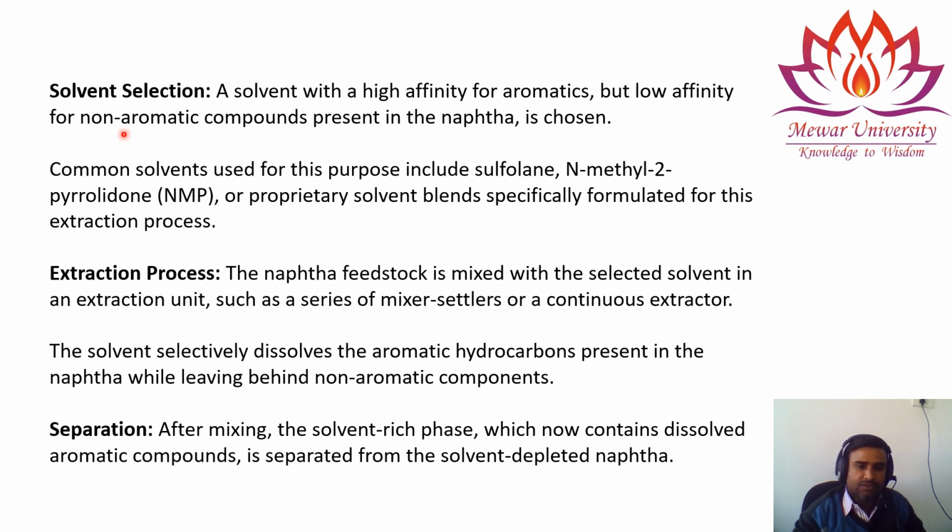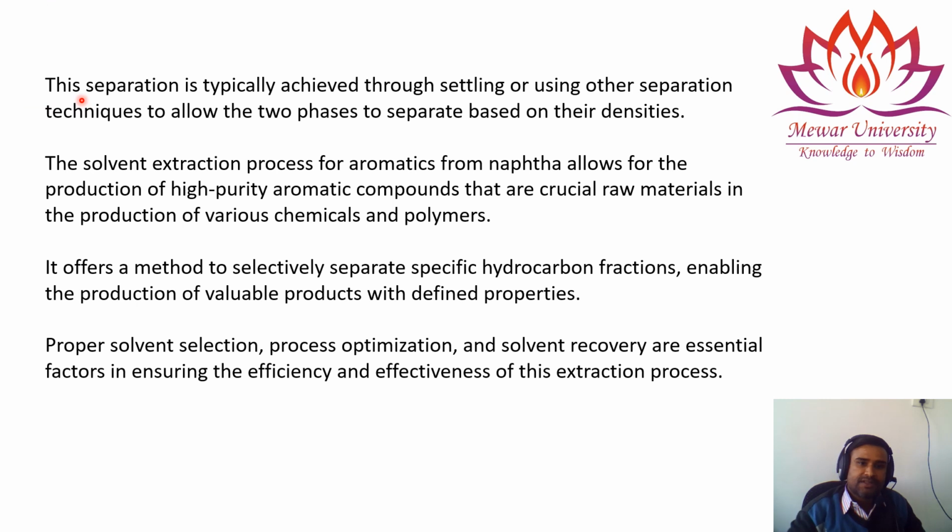Another step is separation. After you mix the non-aromatic compounds, aromatic compounds and solvent, the solvent rich phase, which now contains the dissolved aromatic compounds, is separated from the solvent depleted naphtha. This separation is typically achieved through settling or other separation techniques, allowing the two phases to separate based on their densities. So again we separate the multi-component mixture based on density.